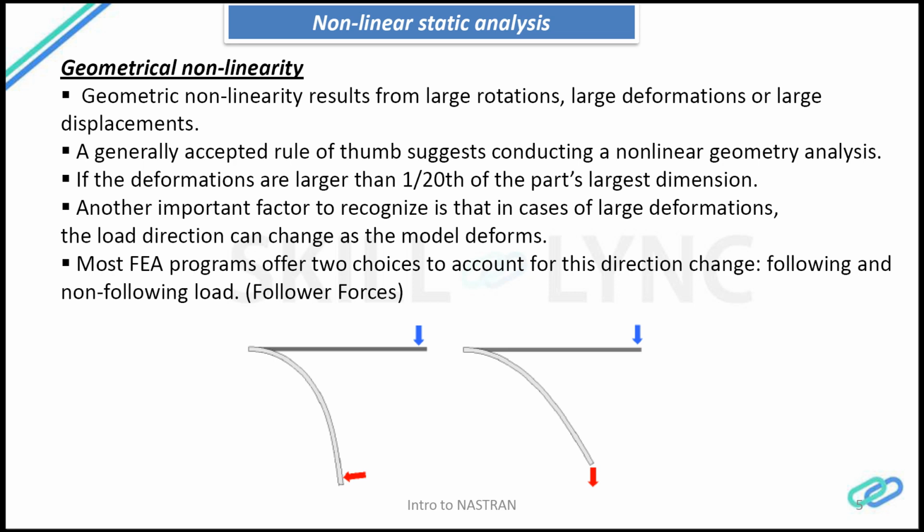Sometimes what happens is an engineer runs the linear analysis, and the results may not be satisfactory, and the displacements might be very large. When he checks the displacement plot, it will show a very large displacement. Then obviously you should rerun the model for a nonlinear analysis just to identify how the structure behaves.